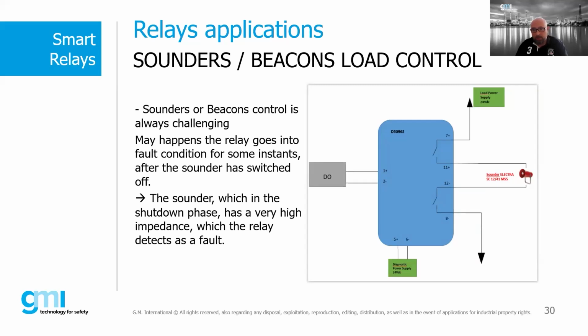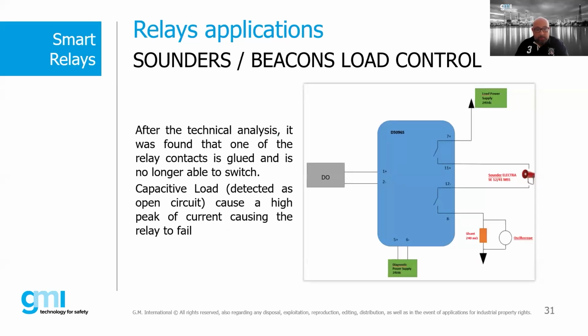Another important thing to know in the next slide is that due to the strong inductive or capacitive front end of the load, it is possible that there are strong reverse current peaks, which may damage the relay contact. To overcome this problem, it is again necessary to insert another device, another protection, such as a PTC, sorry, or a power resistor, able to dampen these dangerous peaks.